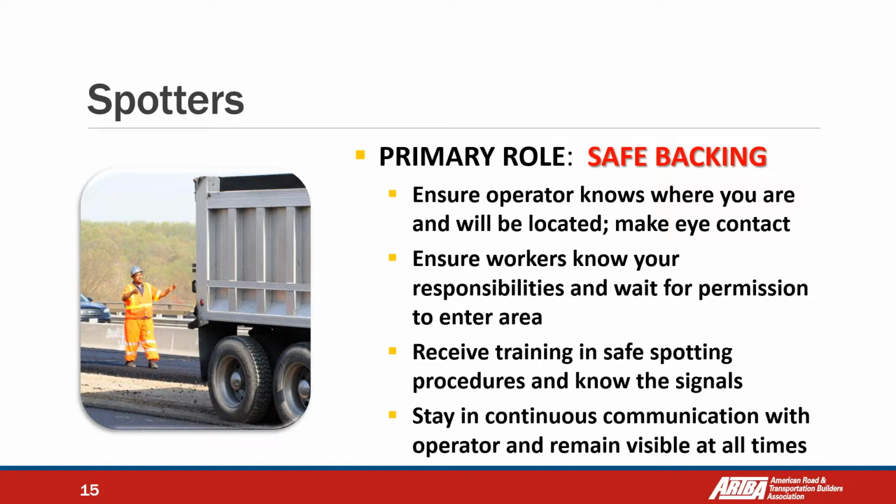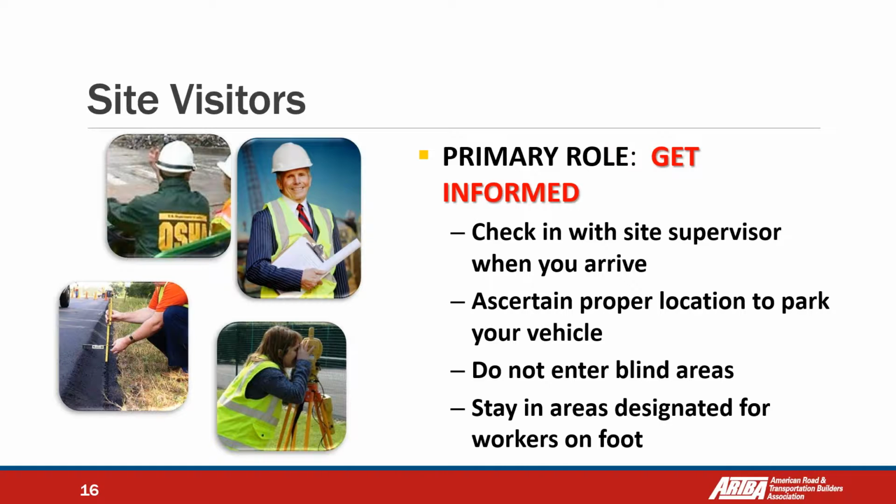Similar to flaggers, the spotters should receive training. It's not mandatory, but it doesn't mean that it is not important. And stay in continuous communication with operators and remain visible at all times. Some basic rules about communication signals: visual contact all the time. If you need to move to another place, you have to ask permission from the operator. If the operator cannot see the spotter, the operator should stop the vehicle immediately. We were talking about all these things yesterday.